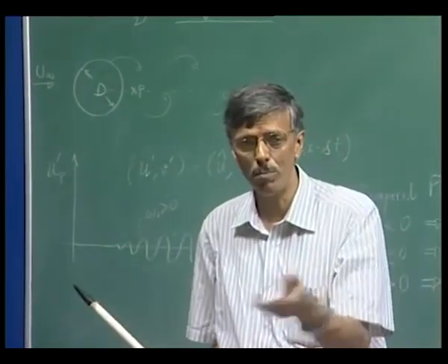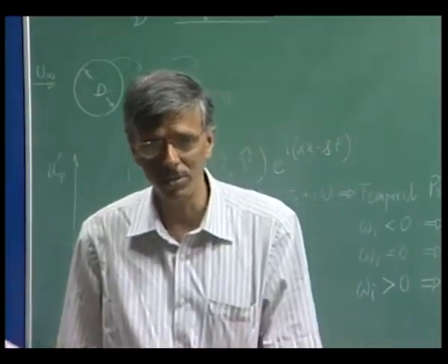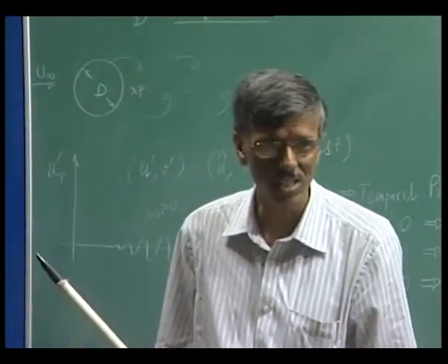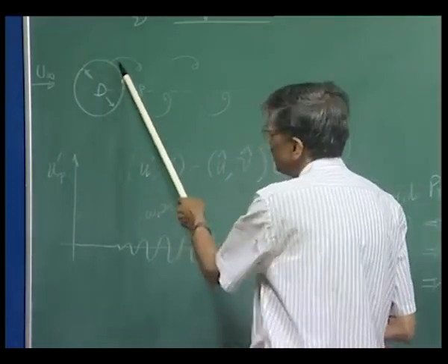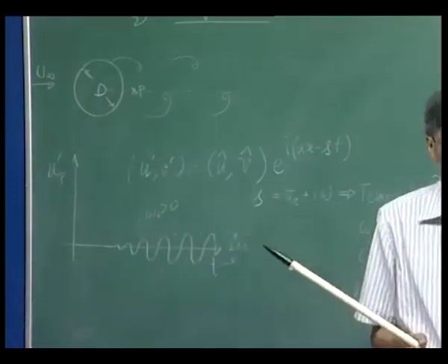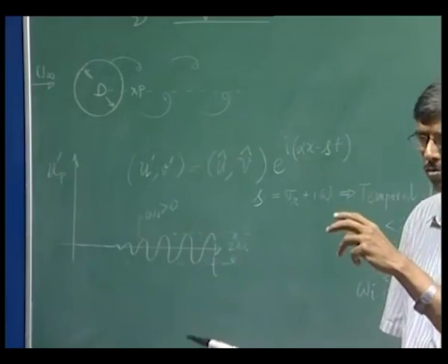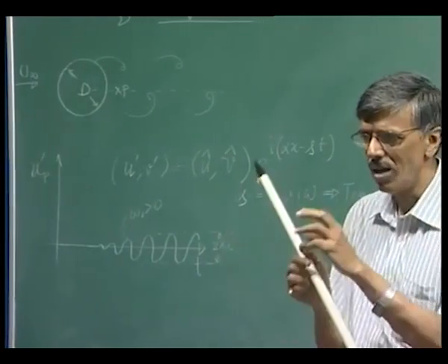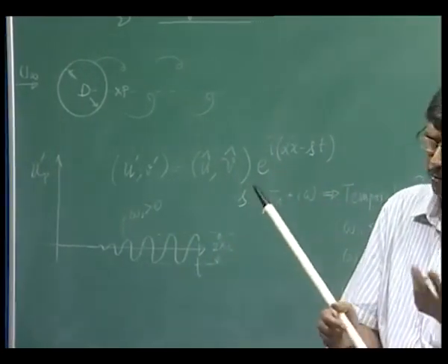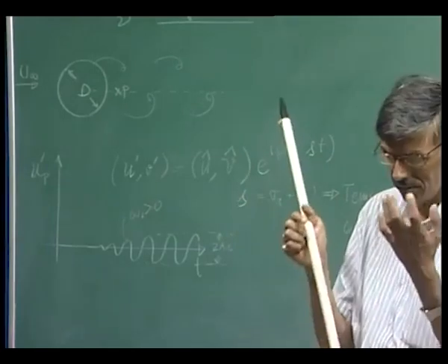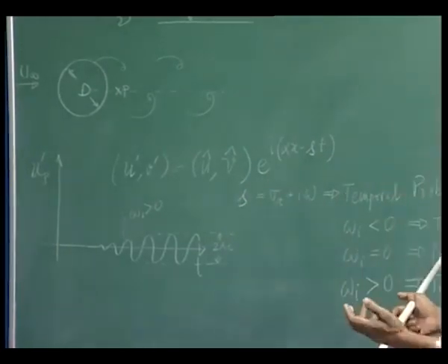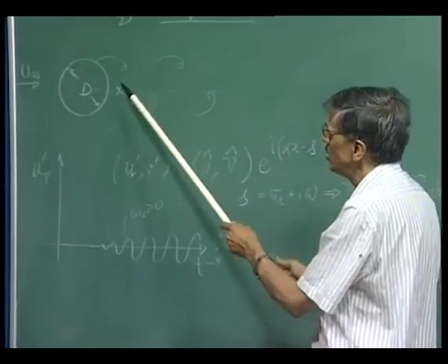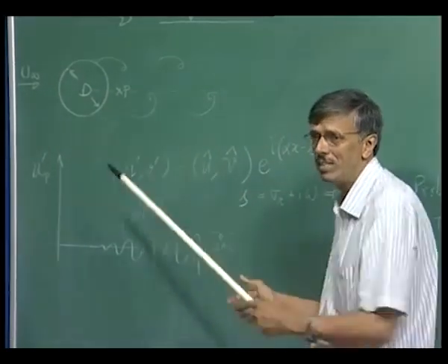It's almost like your pendulum, where the interplay between potential and kinetic energy gives you an equilibrium state. Here also these two vortices do the same thing. So one grows, the other one remains stagnant, and when the one that is growing achieves a certain threshold amplitude, then that is shed, and then the other side starts growing.